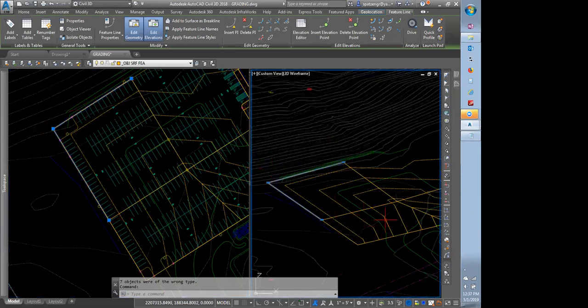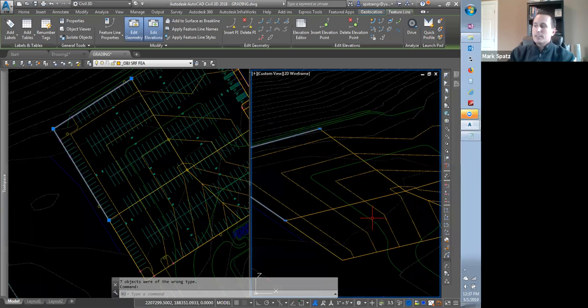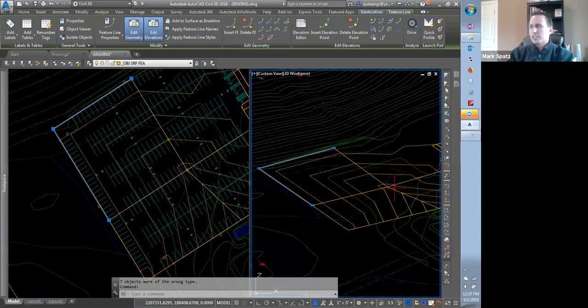But ultimately, you can see the green contour, right? That's what Chris had drawn. And you can see what we're honing in on, although it's not exact, because we don't have the same elevations, and the building might not have been at 608. I think it was close, but I don't think it was exactly. And he might have used different grades. You know, we use 2% and all this kind of stuff.